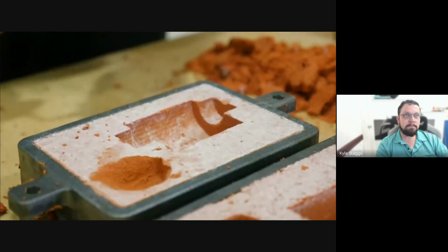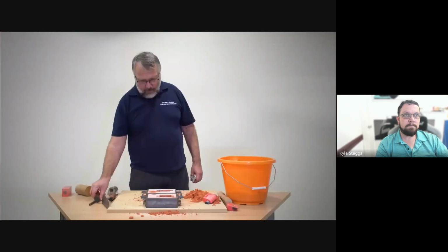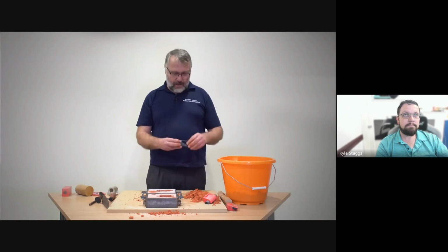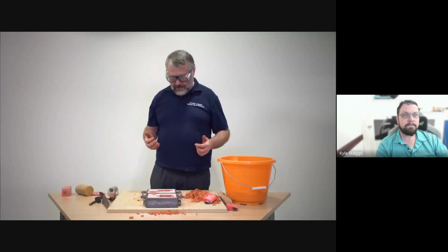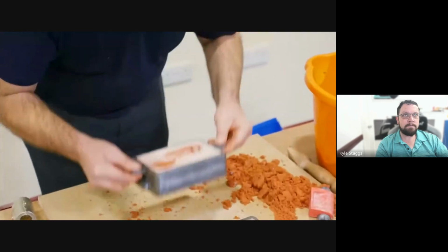The final piece of moulding work we need to do is to cut a gate. We know what a gate is. It's where you go into something, working away from the mould cavity, and we need to ensure that there is no loose sand. A good way of doing that is to blow, and it's sensible to pop on a pair of goggles to make sure that nothing blows back into your eye. So that is the basic mould produced.